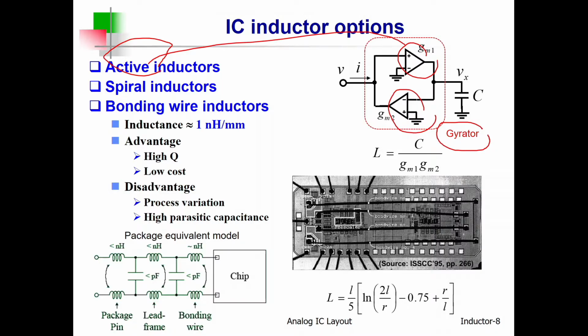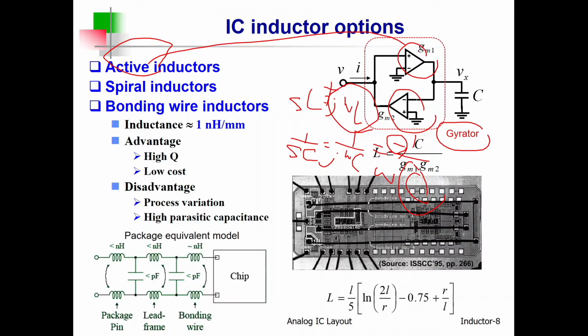For an inductor, you have sL, right? And for a capacitor, you have 1 over sC. So this is j omega L, and that is minus j over omega C. The only difference between inductance and capacitance is the positive phase or the negative phase. So to reverse it, we can make a capacitor become an inductor.